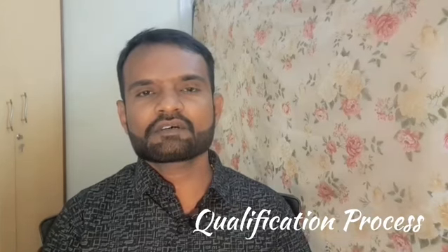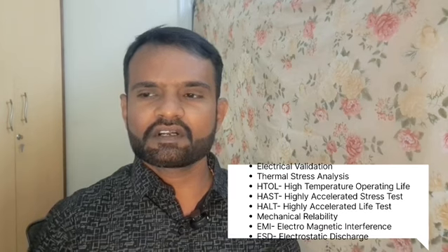See, in many industries, what happens when it comes to qualification, right? We need to understand what electrical validation testing is required, and what the thermal stress is. Basically, in the thermal stress, we have HTOL testing, another one is HAST, and the other one is called HALT. So these are the three different tests which are significantly required when we do any kind of process qualification, right?